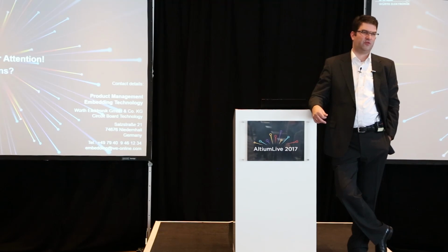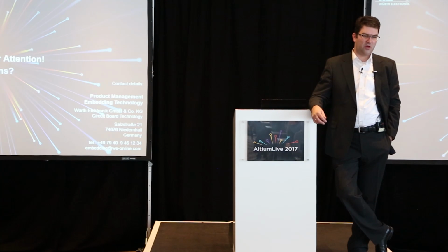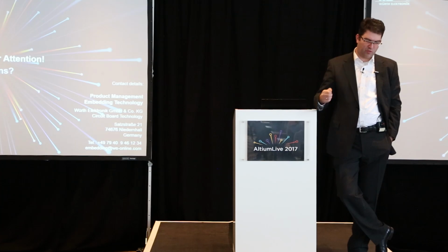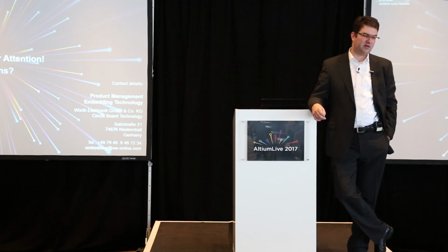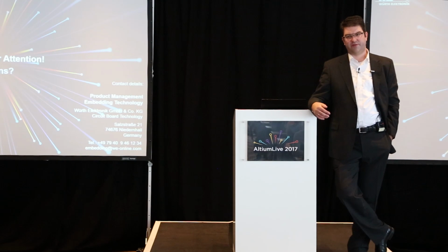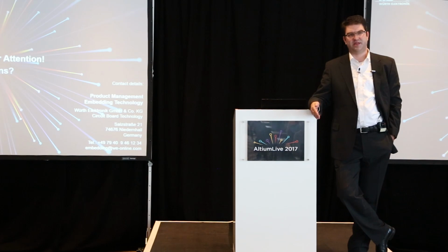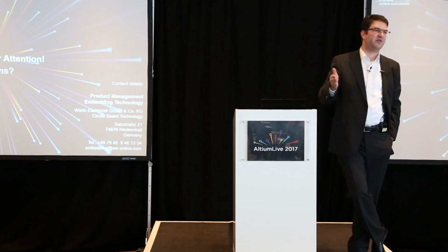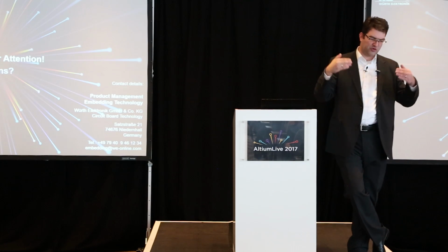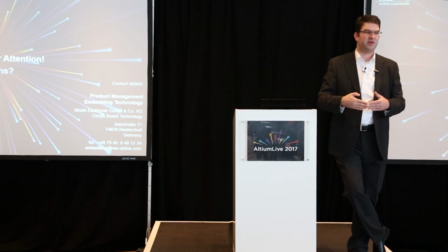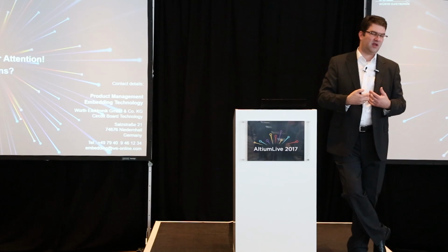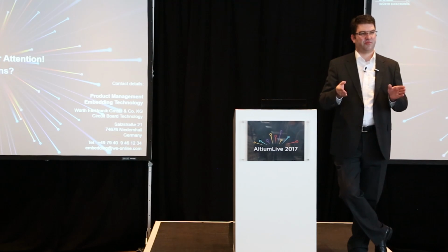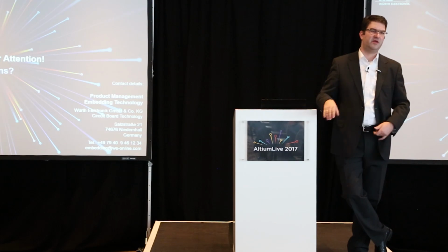Basically, there is a higher risk involved, yes, because you have more process steps. What we try to do is run all these jobs on a higher level in the fab, so that you take more care. For example, in our process flow, we implemented that each core, it doesn't matter if it's ordered by the customer or not, is being looked at in the AOI. So we do what we can to test everything to the max. We do a lot about processes, so the processes are getting better and better.